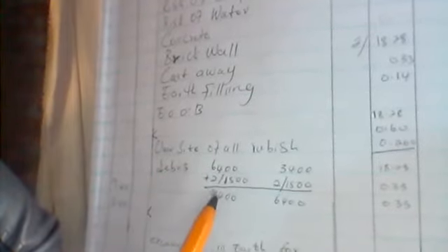Let me repeat it again. We are given the information that for clearing of site it's 1.5 meters. So for us to clear the site, you take this side of 6.4 plus 2 times 1.5 for both sides, which is 9.4, and then 3.4 plus 2 times 1.5 for both sides, which is 6.4.